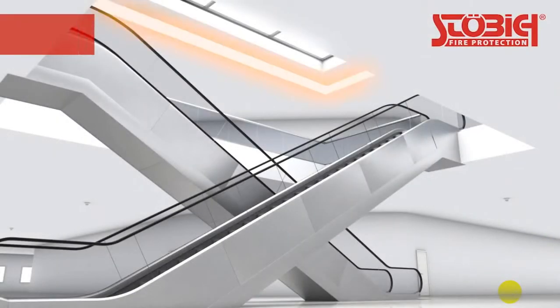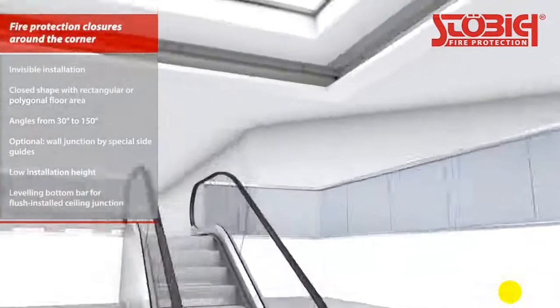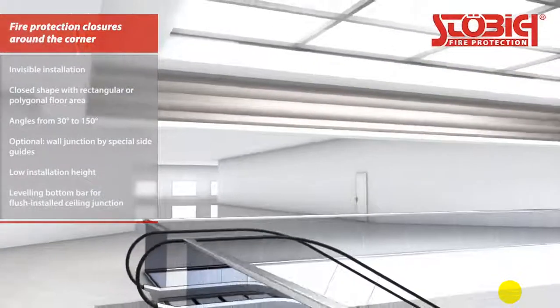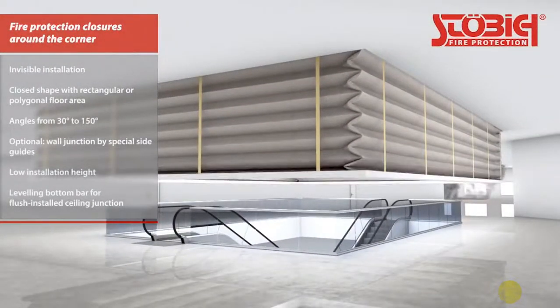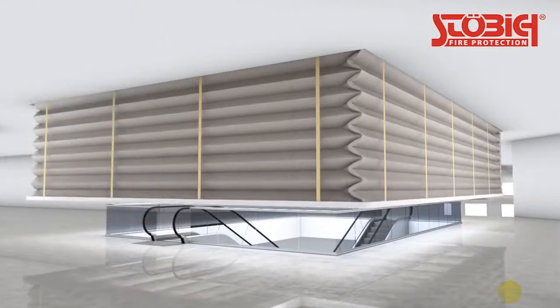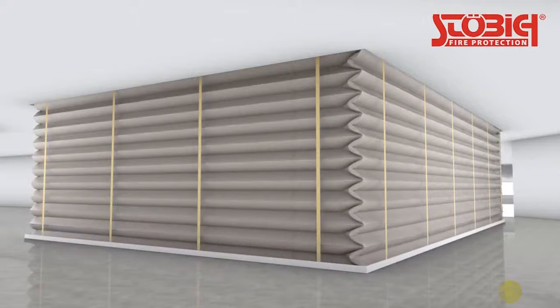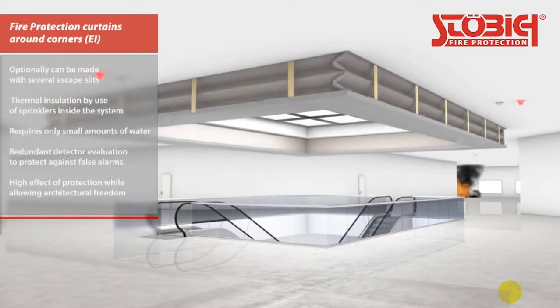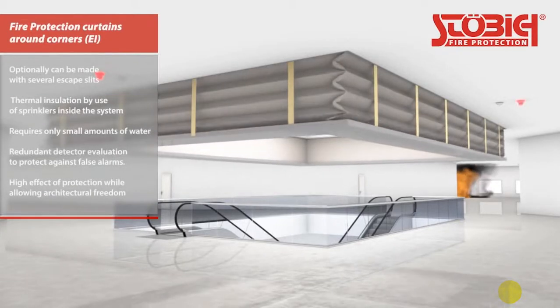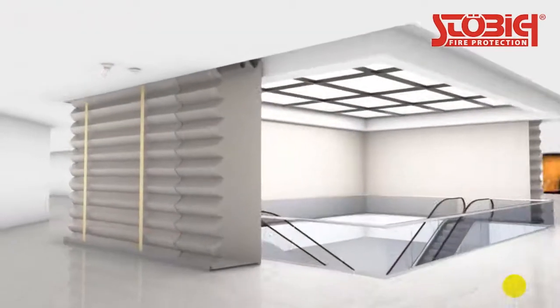Folded and gathered fire protection curtains can be used to seal off spaces in areas with right angles. These flexible systems can be installed along an area's entire perimeter or can end when they meet a wall. In both cases, no additional structural supports are needed in the corner. A design advancement of the folding curtains around corners is the implementation as a thermal insulating system. The EI-120 protection target is achieved through a combination of folding and rolling technology.